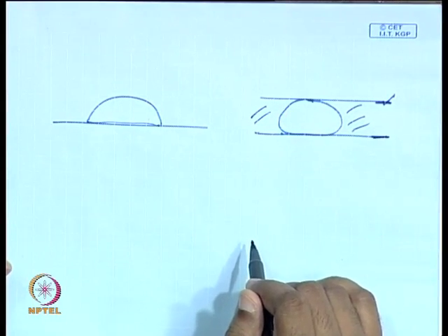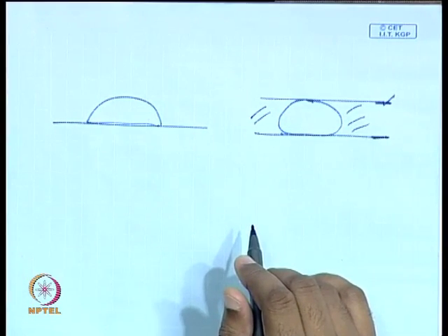Now, let us say you have a reaction which is taking place inside a droplet. Since the size of the droplet is extremely small, the diffusion length and the diffusional resistances to mass transfer would be minimized to a large extent inside a droplet. So, if you have a reactant 1 droplet and a reactant 2 droplet, you could bring them close together, merge them and form a larger droplet. Inside the larger droplet, still very small in size, if it is of microliter dimensions, the resistance to mass transfer would be so small that the kinetics of the reaction can be made faster. So, any reaction which is mass transfer limited would be ideally suited for operation inside a micro droplet.